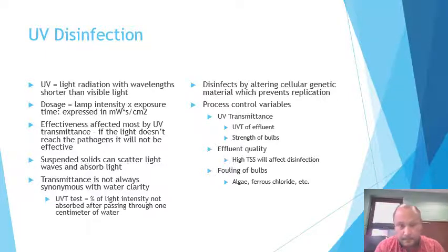So our system, and I imagine almost all systems, are designed with a wiping system to wipe those sleeves periodically and get them clean to allow more light to pass through. But we do have to periodically pull our light modules and physically hose them down to remove some of the algae that gets stuck around the modules. The wipers do a good job of cleaning the quartz sleeves, but they can't get it all.